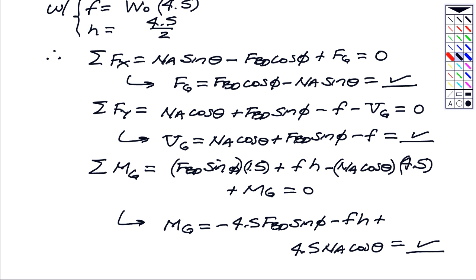So again, our goal was to find the internal force couple set there at G when we made a cut through G. In order to get to that point, though, we had to do 2 steps before. The first thing we had to do was find the external reactions there at points E and A, in particular there at A. The next thing we did, we isolated AC.